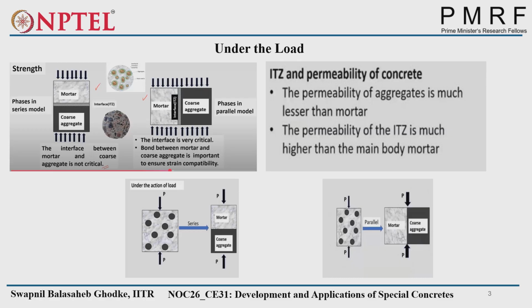The thing is, coarse aggregates are very stiff compared to the mortar, so they will not deform easily. The mortar will deform. Here also it tries to be similar, because the interfacial transition zone bond maintains a similar deformation.